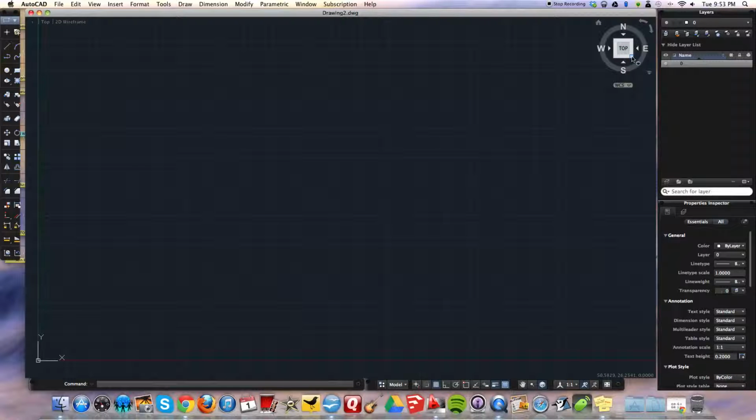If you hover over the view cube, you'll see certain areas light up on it. What I want you to do is click the top between the east and the south. Okay, so this little tiny corner. Click there. If you don't click in the right place, it's okay. You can get to this point, okay? And this whole screen flipped so that it's on its side, so we now have a z-axis which pokes out at us, which gives us 3D. So we have x, y, and then z coming up.